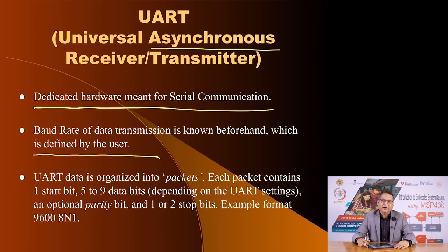Also, since you are sending data serially, for historical reasons, in the olden times you did not want to send 8 bits of data. In fact, if you recall, the original ASCII standard is defined for 7 bits. So if you wanted to send ASCII information, you only wanted to send 7 bits. But these days you want to send the entire 8 bits of data, and in fact there is an additional extended ASCII format which allows for 8 bits. So you may choose to decide how many data bits will be sent in each transmission, and together with the rest of the bits we call this one data packet.